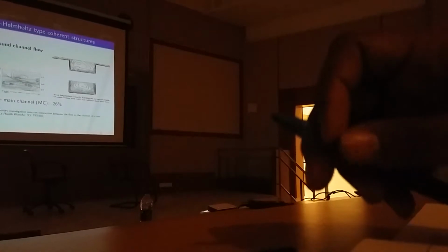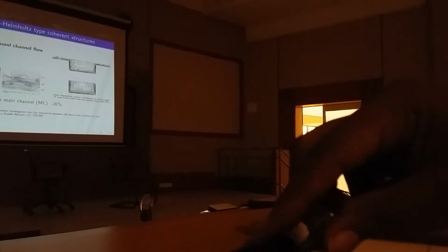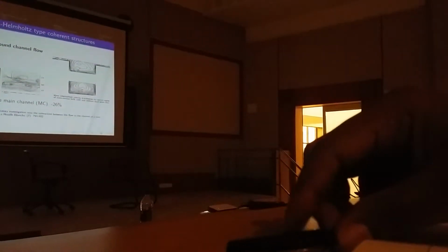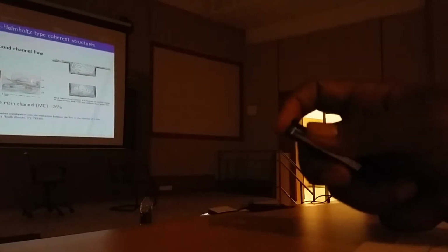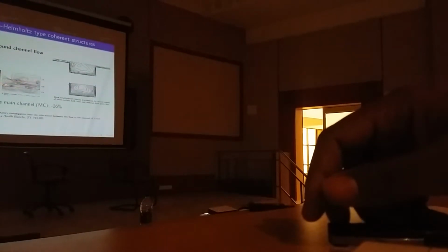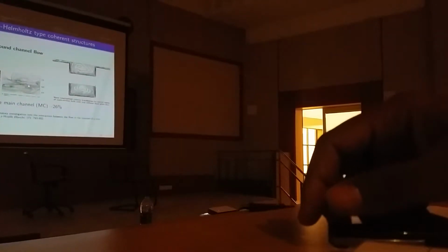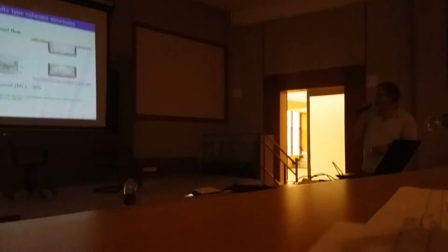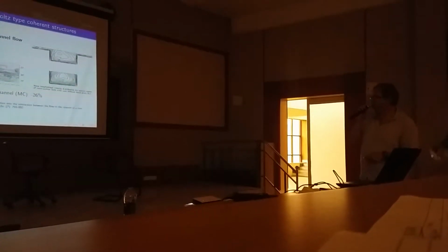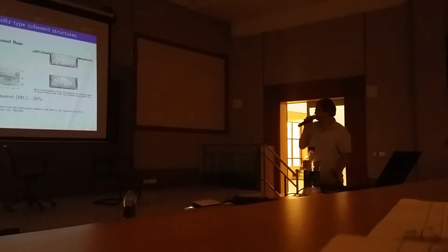So, second point of the context, these vortices, these coherent structures, were first studied by Sellin in 1964 in the lab. Here you can see the main channel, here the floodplain, and you can see a big horizontal structure here with the core at the interface between the main channel and floodplain. Here, this is a picture of the water surface with seeding. He put seeding on the water surface, and you can see the strong vortices here.